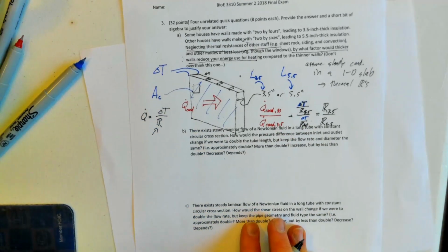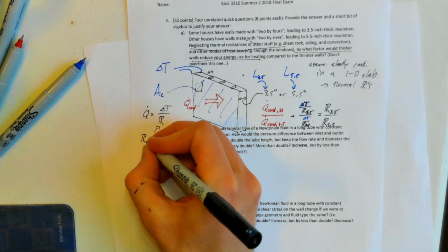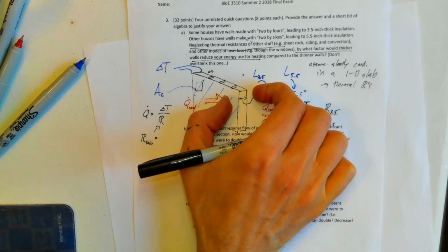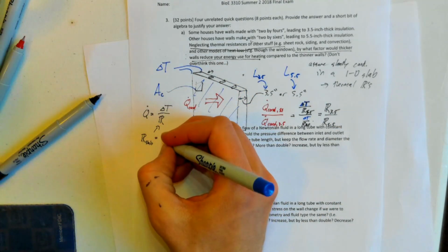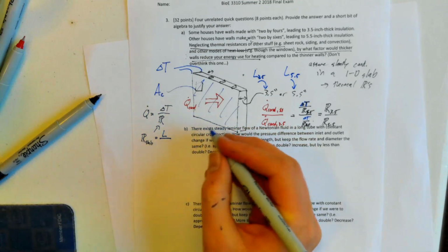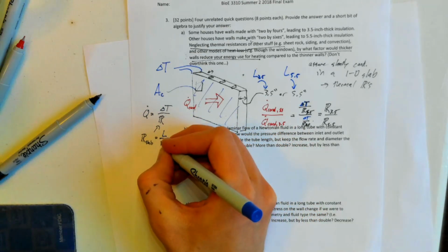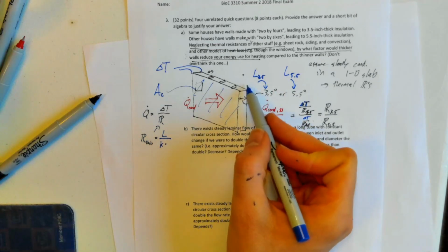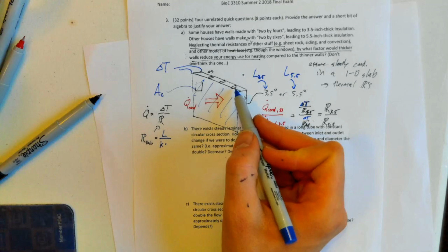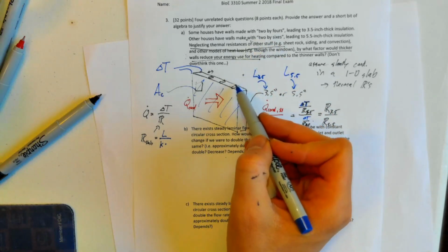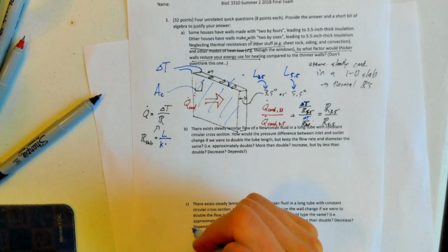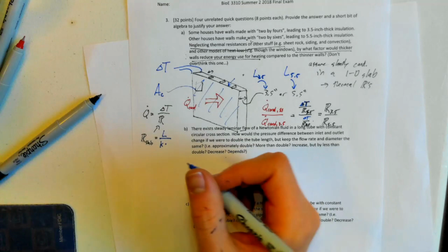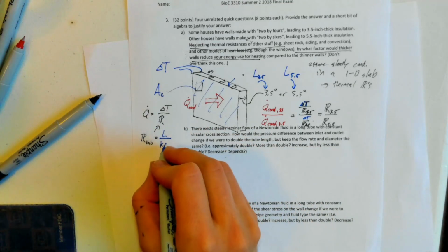For the 1D slab, the thermal resistance is proportional to the thickness. Thicker walls are better thermal resistors, divided by the thermal conductivity of whatever makes up the insulation material, which, regardless of whether you use 2x4s or 2x6s, you're still putting that pink fiberglass insulation or whatever insulation you have in those spaces. So that's going to be the same for both of them,